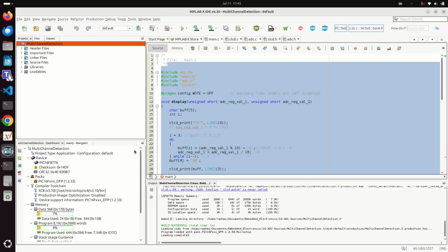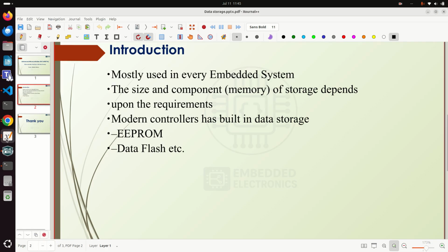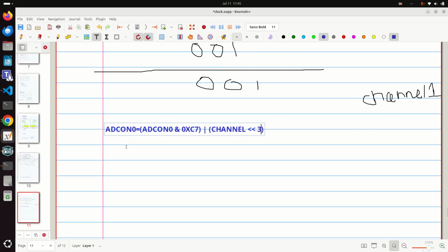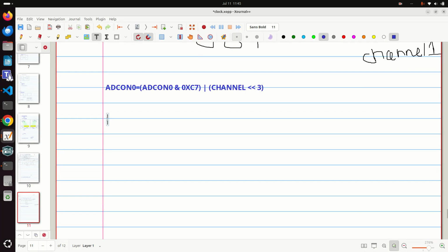So let's implement an up counter on each key press. When you press the key, the value should increment. Count up to 9 on every key press. Once the count exceeds 9, it should be reset, so it rolls back to 0.